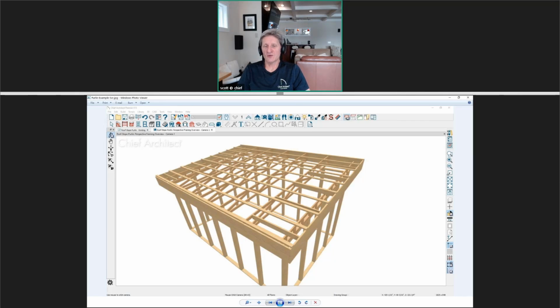So currently the roof, when you are building it, as you already know, it sounds like, you can only choose either plumb or square. If you don't want to do the entire house, you could just take a small section right through one of those beams, create your polyline solid, and then just remove the fascia off there and draw that in with a polyline solid, just in that one section view, so you have that view. You wouldn't have to repeat that or extrude that for the entire design if you didn't want to. So that'd be pretty quick to do. Does that help a little bit?